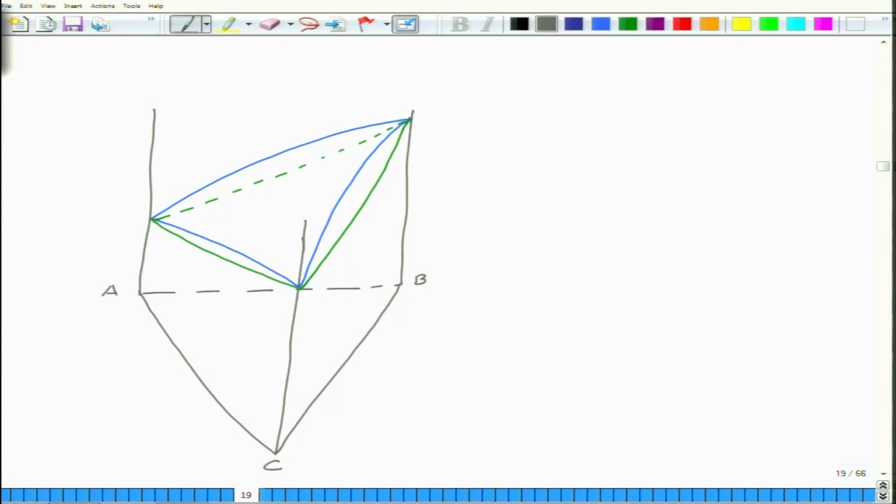So, this is how the phase diagram will look like. So, you have liquidus, this is solidus. So, phase fields will be, you have liquid here, in between these two solidus and liquidus you will have liquid plus solid, and then somewhere below the solidus you will have only solid.